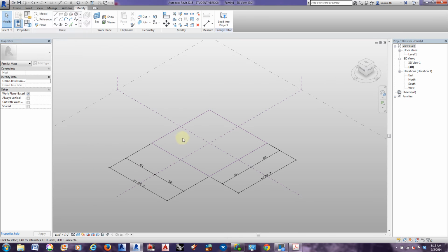So we're going to create a form, a solid form, and we're going to pick the extrusion. And notice there's a dimension here. I'm going to go ahead and click this dimension line little button, which makes it a permanent dimension. And now I'm going to make a new parameter for that dimension. We're going to call that H. Say OK. And now let's see if this works. And it does.